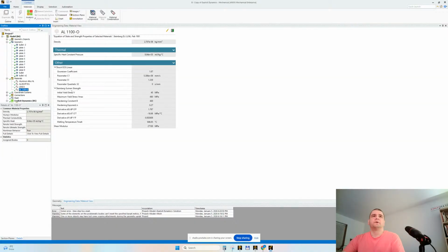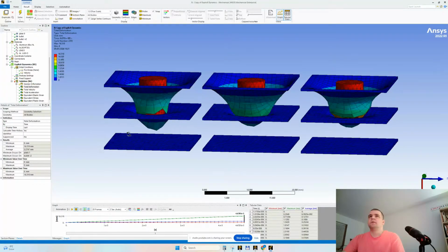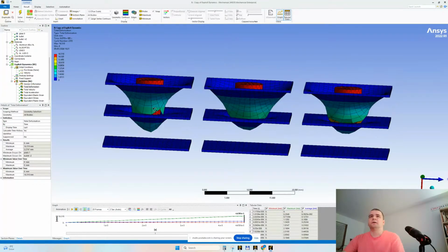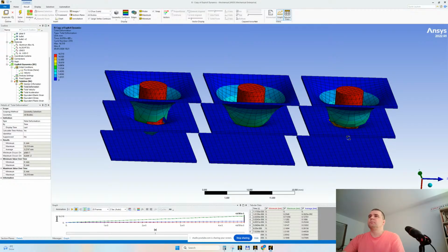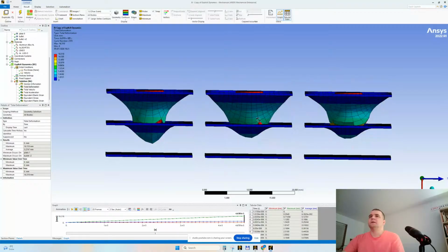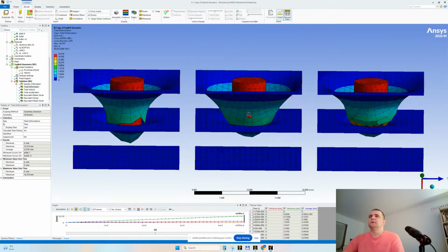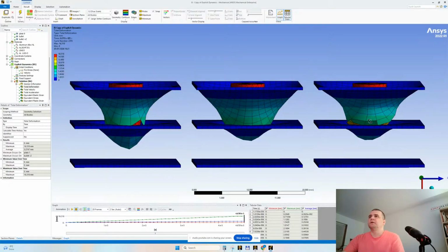The aluminum with Steinberg-Guinan broke a little, but not too much. And the aluminum with Johnson-Cook broke much, all right? The aluminum defined with linear isotropic hardening did not behave correctly, okay? We should have breaking.